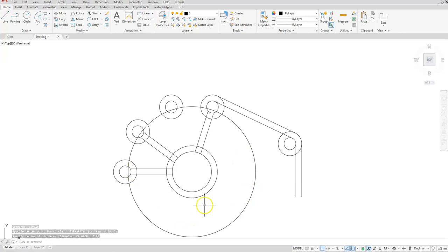Okay, so let's start cleaning this up. Let's go ahead and trim. I'm going to start with the inside of this circle, so I'm going to trim here and then there. I'll do the same with my next circle here, so I'll trim here and there. With this circle, I don't have that option. Well, I do. I'm still going to do the insides here, all around it. Then I'll come to this circle here. So I'll start here, and I'll work these 2 points on the outside.